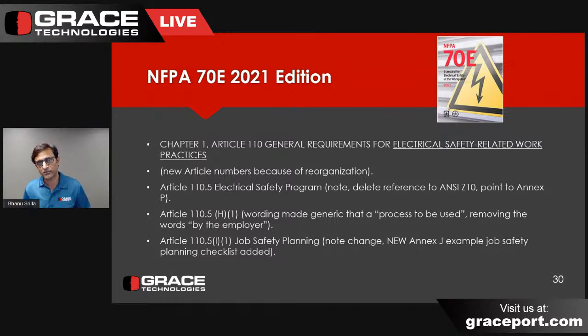If you don't have the manufacturer's instructions, then you can go to industry consensus standards. For example, if you're using a piece of switchgear that's 3 or 4 decades old, and you don't have any information or background on that equipment or the manufacturer, or it is an imported item, you can look at the recommendations for that type of equipment in the NFPA 70B standard or ANSI NETA MTS, if it is electrical equipment. Any additional thoughts on that, Terry?